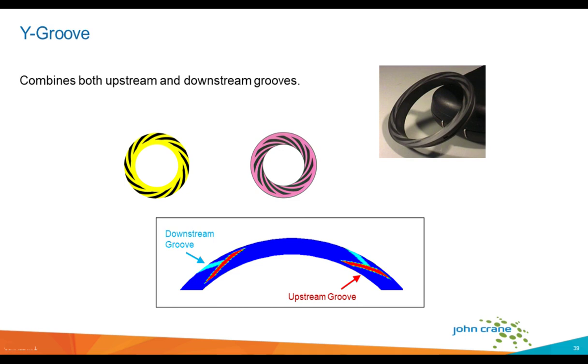And as we meet that intersection and we channel some of that oil back to a termination point, we create a higher pressure due to that groove tip termination. And at that higher pressure, with that pressure spike, you're creating hydrodynamic load support purposely. By doing that, you add a lot of stability to the overall seal face, and you're ensuring lubrication and stability of the interface gap.